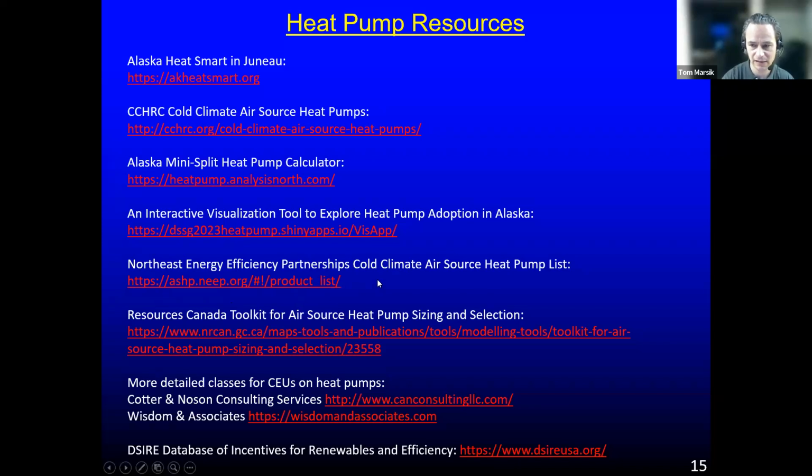The one you'll be likely looking at if you're looking at the efficiency is something we call the HSPF, Heating Seasonal Performance Factor. It's actually something that relates to the coefficient of performance. The kind of tricky part nowadays with the heating seasonal performance factor is that there is a new test procedure for that, and the results of the test procedure then give you what's called HSPF2.